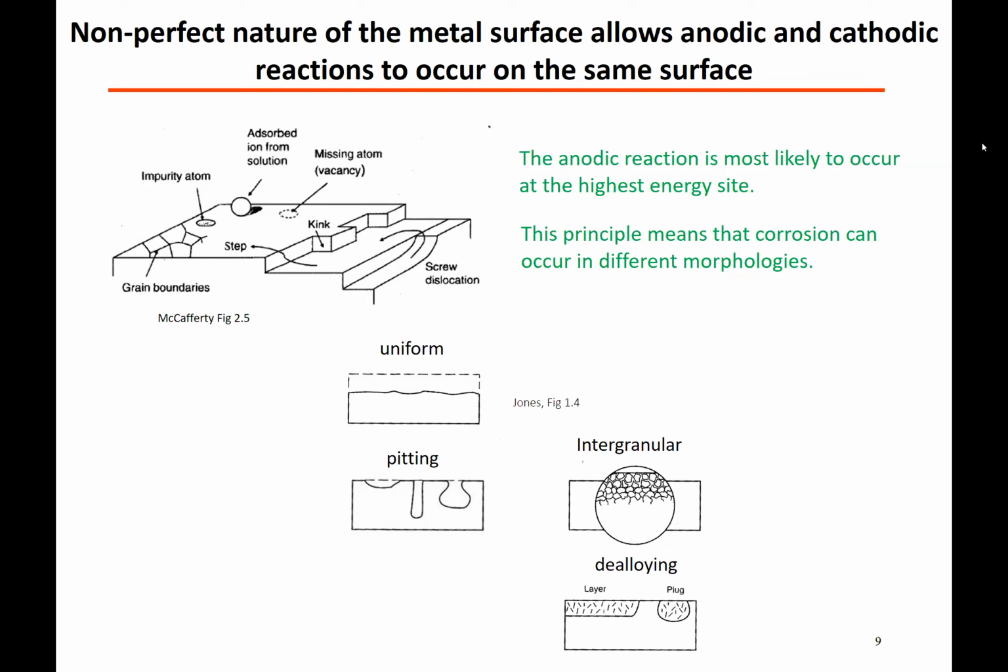So we talked about how grain boundaries can actually be the site of corrosion as well. We talked about the result of the corrosion in which we can see pitting, as you can see here. And we talked about how some of the cracks that form will crack right through the grains along some crystallographic direction.